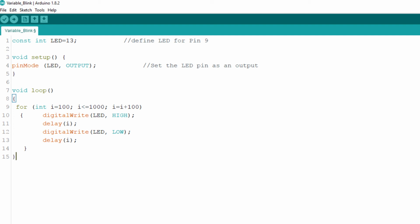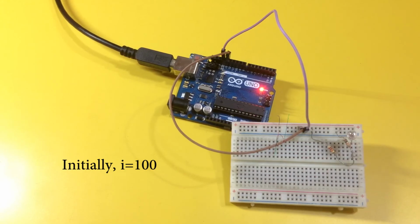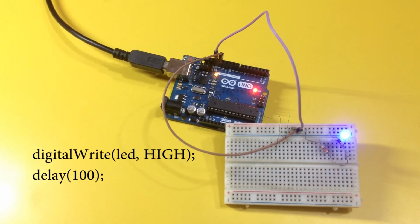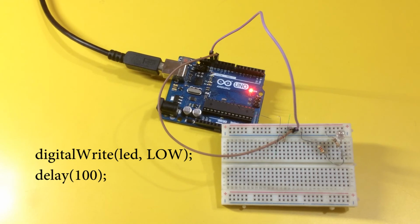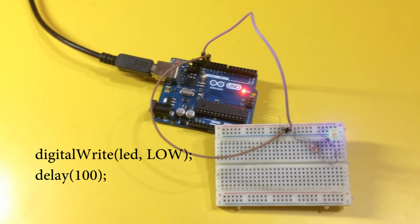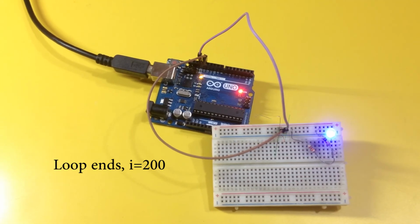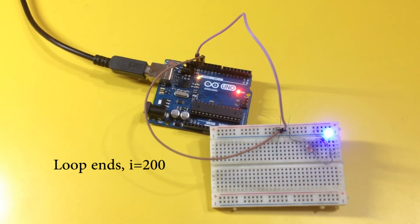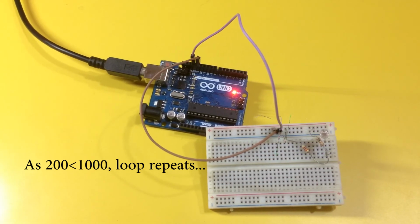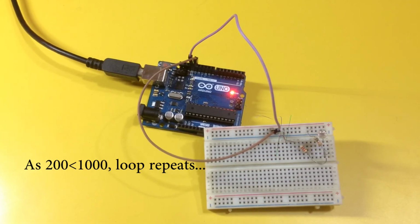To better understand these concepts, consider what happens in the two passes through the for loop. Number 1, i equals 100. Number 2, the LED is set HIGH and stays HIGH for 100 milliseconds. Number 3, the LED is now set LOW and stays LOW for 100 milliseconds. Number 4, at the end of the loop, i is incremented by 100, so it is now 200. Number 5, 200 is less than or equal to 1000, so the loop repeats itself again.